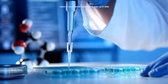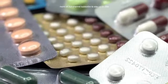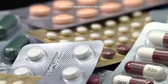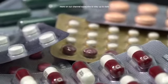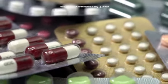For instance, validating a tablet compression process would involve multiple batches produced under defined parameters to demonstrate that the tablets consistently meet specifications for weight, hardness, thickness, and disintegration. Validation provides the scientific evidence that your manufacturing process is in control and capable of consistently producing quality products.